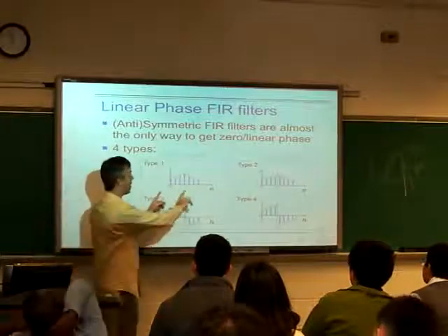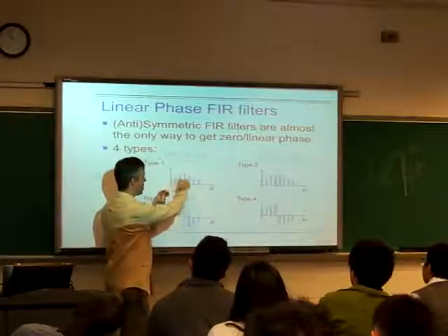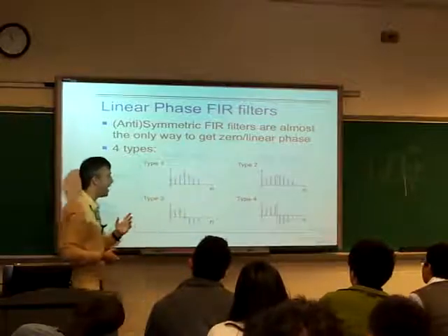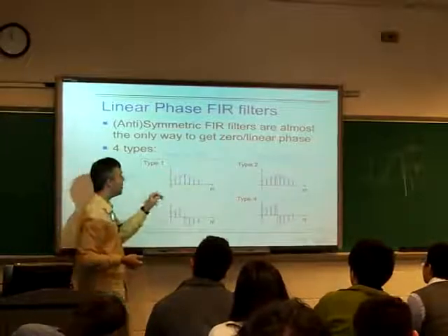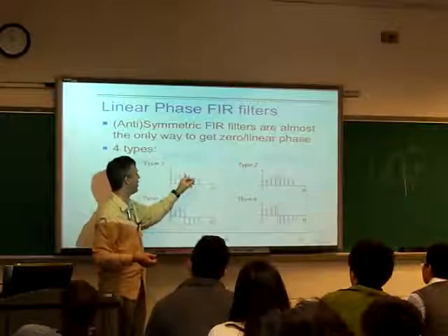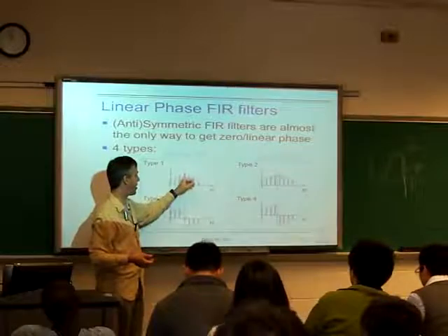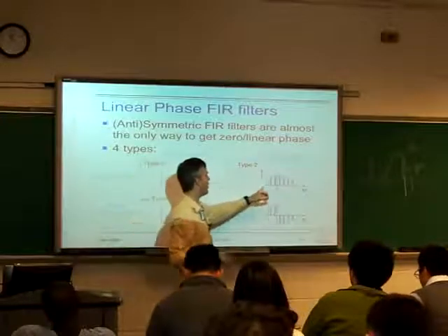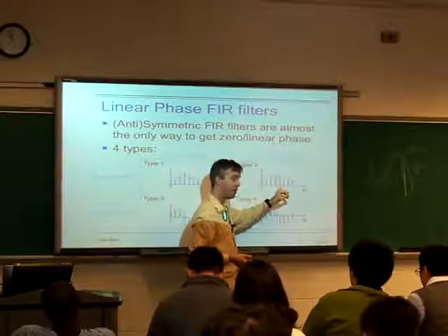We're going to have a finite impulse response system, so it's a finite length filter, but the impulse response is going to be symmetric in time. It turns out that there are two kinds of symmetry here. Symmetry about a single point, a symmetric point in the middle where we've actually got a sample, or symmetry where you don't have a point in the middle, where the middle is midway between two samples.